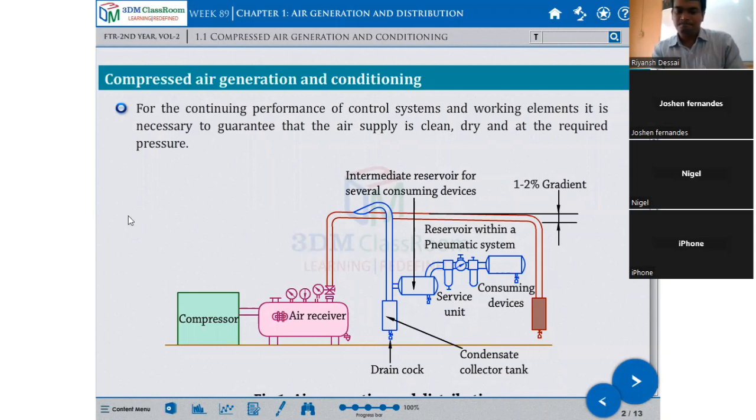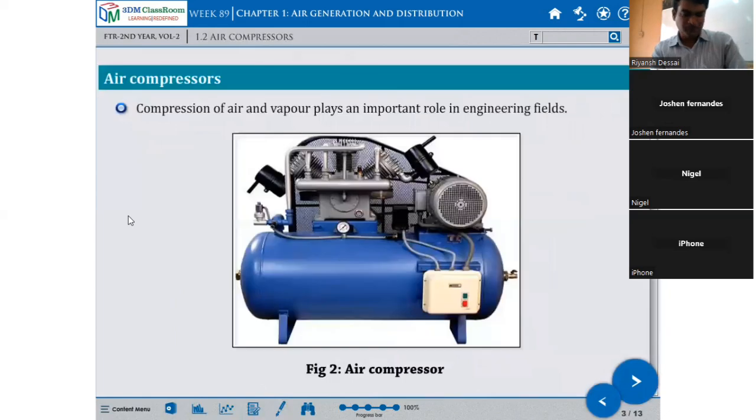Compressed air. Okay, the air compressor is shown here. Again, the same picture has been used here. So these are the 2 suction ports here, black color, open to the air, as you can see. Whatever atmospheric air there is gets compressed here and is sent to this header, and then to the air receiver. All the cylinder discharge lines are connected here. You can see this is connected here, this is connected here, and this one is connected here. So the common header is here, and then it passes on.